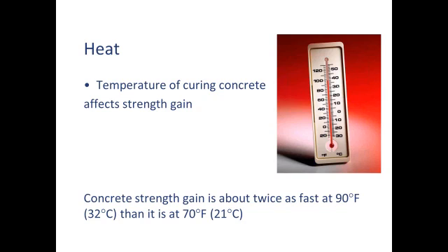That's why a lot of precast concrete is steam cured, because they raise the heat in a gentle, controlled fashion to a moderate temperature, perhaps 120 degrees Fahrenheit, maybe a little bit more, and hold it there for 8 to 12 hours or so. It's kind of like the concrete sits in the forms for 2 to 3 times that length of time. Maybe 12 hours at 50 degrees centigrade is kind of like 36 hours at 20 degrees. So if you can give your concrete heat, you can really buy yourself some time. And always remember, concrete generates its own heat. So if you just put insulation on it, you can trap the heat it makes.